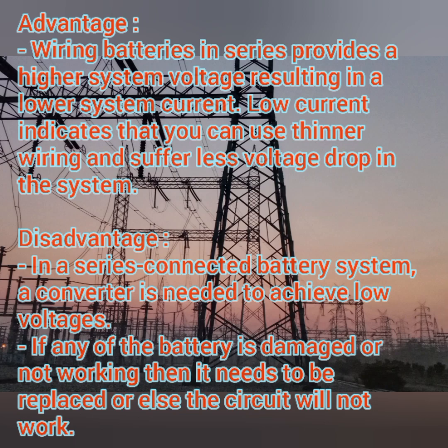Then the series connection is a chained connection. If any damage or break happens in this chain, our circuit will be in an incomplete condition, so there will be no more working in the series connected batteries. So we need to replace that individual battery, and only then can we restore the system.